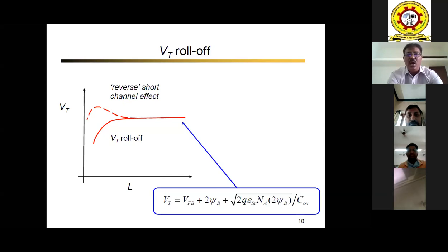What is halo doping? Halo doping is, in certain advanced devices, where they vary the doping levels at the source, at the channel, and at the drain. So they increase high-end doping at the source as well as high-end doping at the drain compared to the channel. That causes your depletion layer at the drain end to penetrate deeply because of the higher doping, and sometimes it may even touch your source. Thereby, certain voltages are internally developed at the substrate level itself.